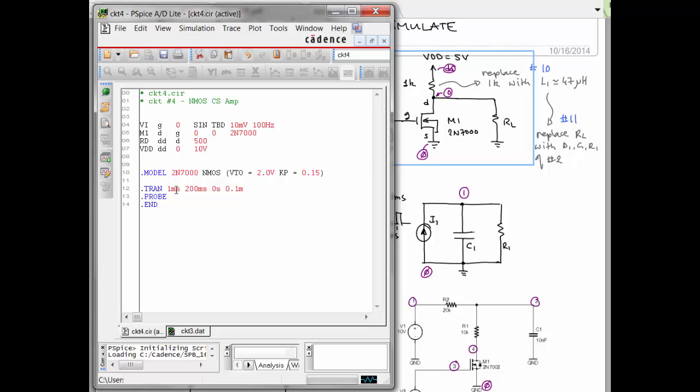We're going to run our simulation. So what we're going to do here is we're going to run 2 simulations. First, we need to find out what offset voltage we should apply here. We can do it 2 ways. One way is we can just run a transient simulation, and the duration we should run for this is, at 100 hertz, a period of 10 milliseconds. So let's do 80 milliseconds. That'd be 8 cycles. Let's go ahead and try to run this.